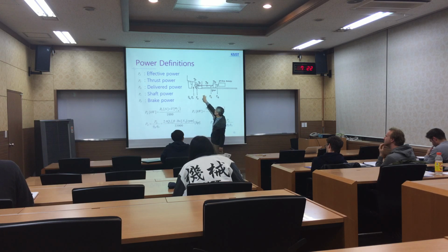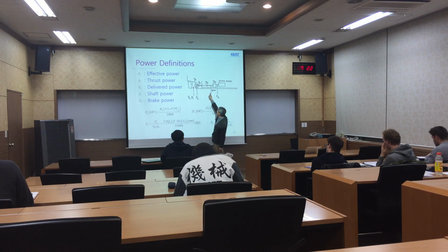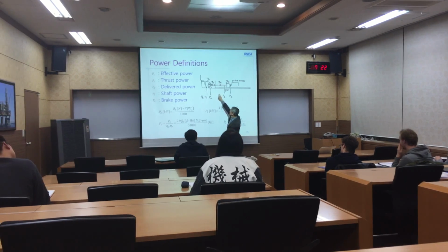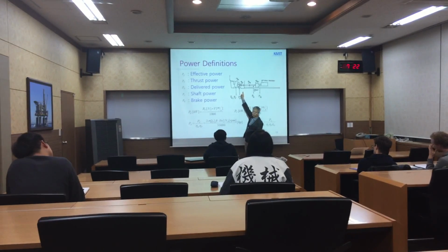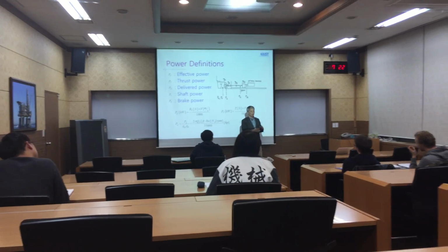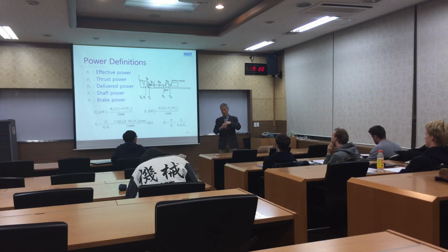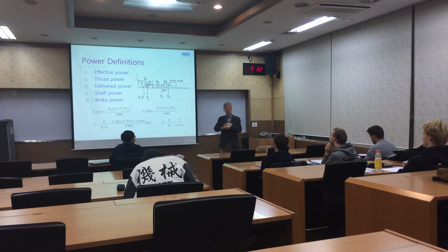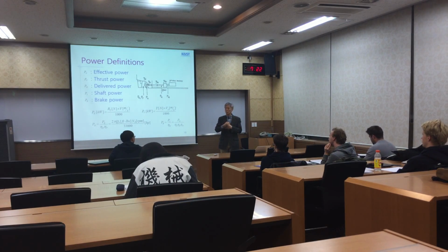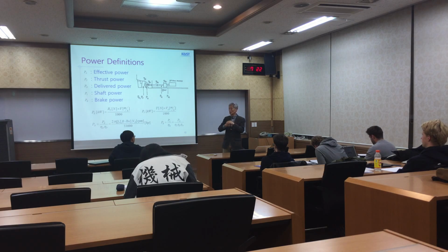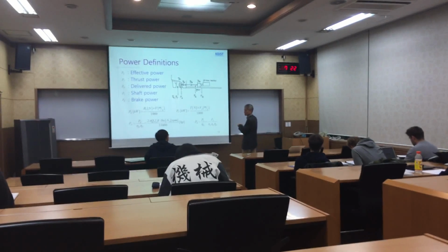So shaft power is behind the gearbox, and there are some bearings because the shaft is long. And finally, the stern tube. The stern tube is a tube that holds the final bearing, and because outside is water and inside is air, right? The stern tube is special. It is waterproof, right? So it creates more loss, efficiency loss.